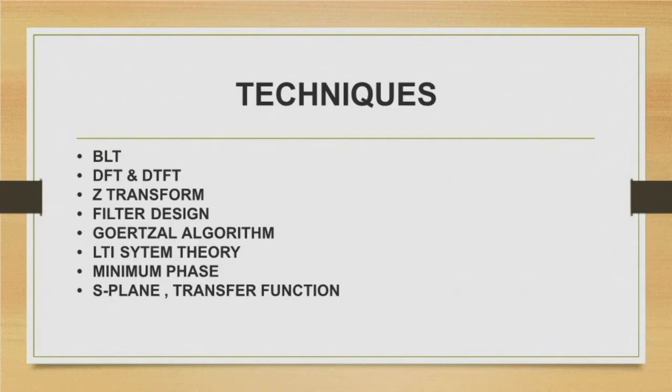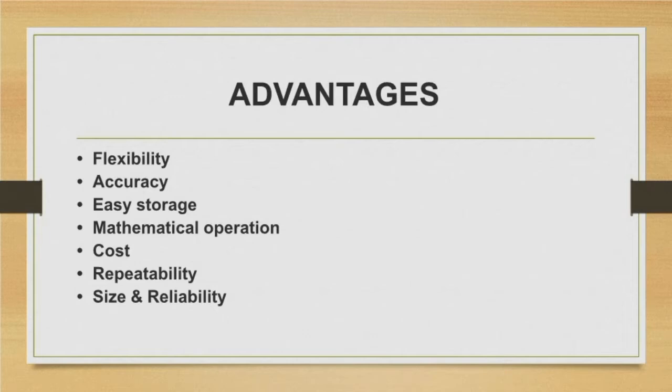So what are the advantages of DSP processor? Before entering into these advantages, you must know how signal processing can be classified. What is signal processing? Signal processing is the operation that changes the characteristics of a signal. Here the characteristics mean the amplitude of the signal, or phase of the signal, or shape of the signal, or frequency content of the signal. So there are two different types: one is analog signal processing and another one is digital signal processing.